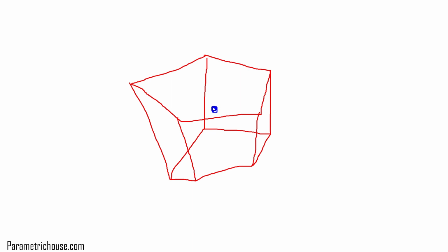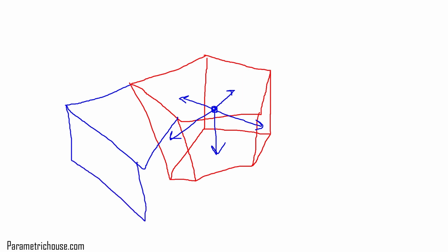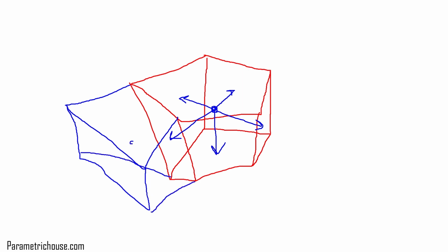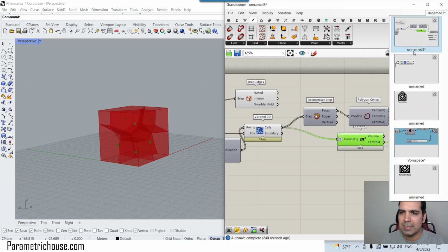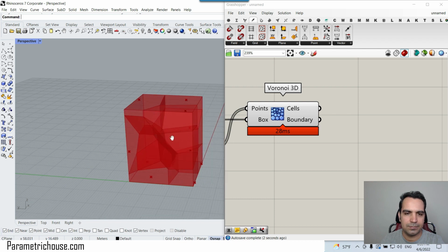What we want to do is to connect the center to the area centroid of each of these faces. Okay, this is going to give us the node which we need, and also those lines are going to be connected, because if we have another cell, a neighbor cell here, for example, okay, I didn't draw this one good, so assume that this is the neighboring cell. This is also going to connect to the same point as the neighboring cell, and that is going to give us a good connection. So that is really easy, and we just have to find the centroid.